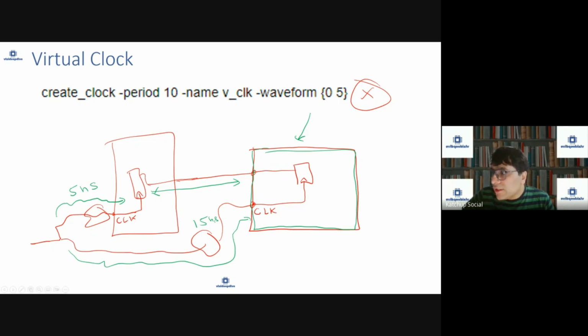Okay. So the delay, let's say the delay of this logic is 10 nanoseconds, but delays are specified with respect to a clock. So this delay of 10 nanoseconds is with respect to the clock net, which was coming here. Let's call this net X, and let's call this net Y. This delay is with respect to net X. Now in this design, let's call this B and call this A, net X does not exist, right?